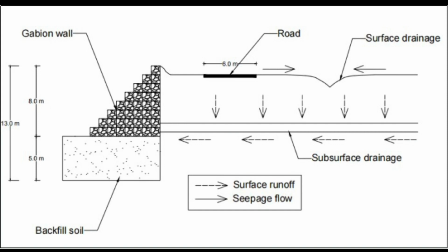Gabions are used to create an outlet protection system for horizontal drain holes. In the absence of outlet protection, erosion brought on by the accumulated water will be active and lead to the collapse of the outlet.